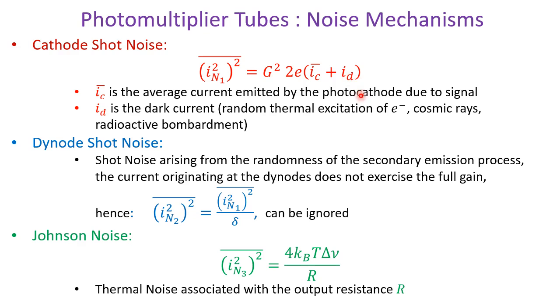And similarly, there is always a background of cosmic rays, which is coming from the sun, for example, our nearest star. There is a radioactive background which is always there on Earth. So all of these actually have sufficient energy to basically drive the dark current in this. So even when my signal is completely off, I would still get this dark current, which is released from these other extraneous sources of energy, right?